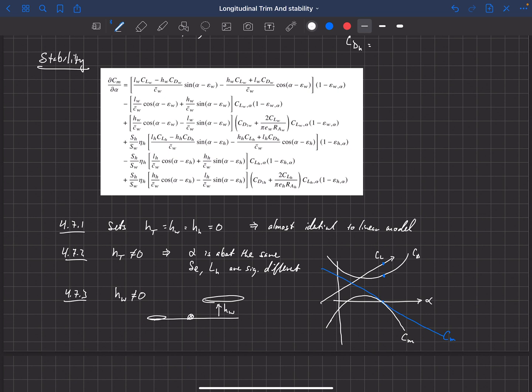And so this opens up a really good discussion on pitch stability. Now, technically speaking, this aircraft is still stable in pitch around that trim point. So if this is where we're trimmed, our first derivative of pitching moment with respect to alpha is negative, and so we're still stable because we've got a negative Cm alpha there. And actually we're stable if we move back here. This is the point where we would get the largest restoring pitching moment.